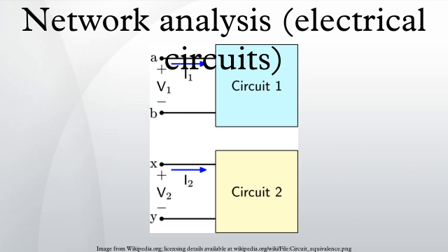The piecewise method is similar to the small signal method in that linear network analysis techniques can only be applied if the signal stays within certain bounds. If the signal crosses a discontinuity point, then the model is no longer valid for linear analysis purposes. The model does have the advantage over small signal, however, in that it is equally applicable to signal and DC bias. These can therefore both be analyzed in the same operations and will be linearly superimposable.